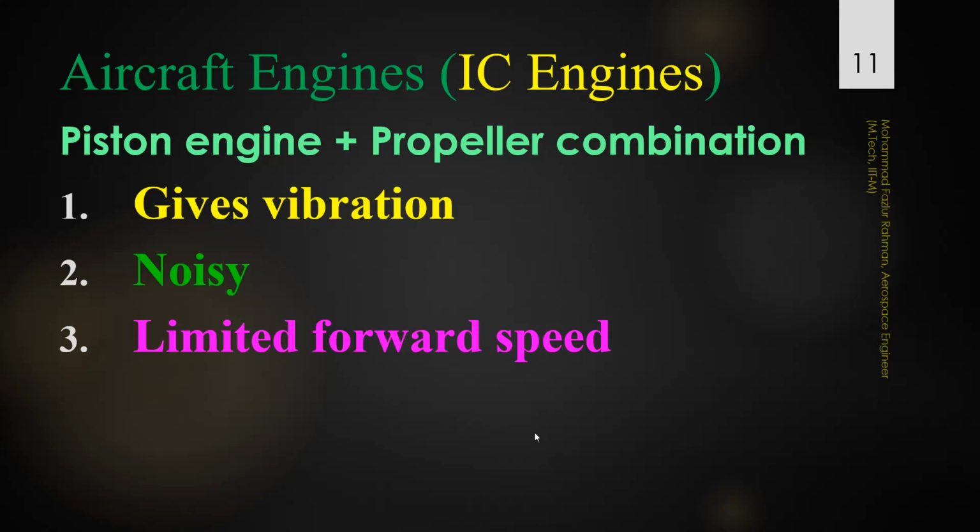The tip of the propeller has the maximum radial velocity. Hence, the propeller tip reaches the sonic barrier first if the velocity keeps increasing. The moment the tip becomes supersonic, shocks are generated and they stall the performance of the propeller. We call that tip stall.